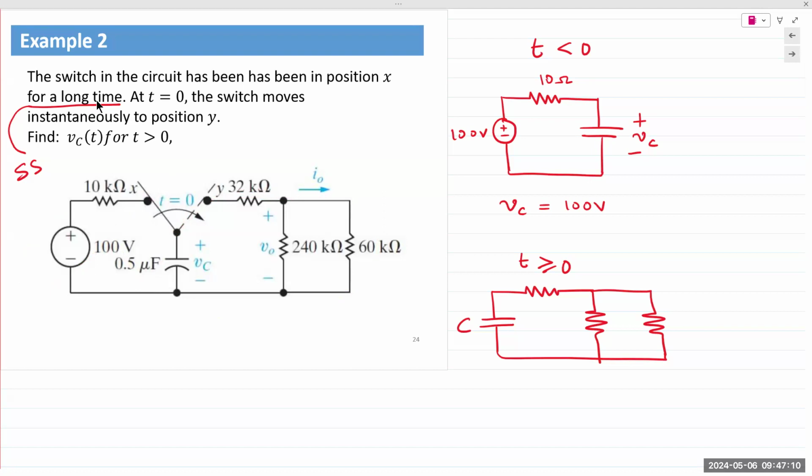Oh, you mean voltage drop across that resistor? It won't. The question being asked is, would there be a voltage drop across that resistor? The answer is no. The explanation is that when it first begins charging, yes, that resistor will have a certain amount of voltage drop, and so the voltage across the capacitor will build up slowly. Once the capacitor reaches full charge, it behaves like an open circuit.